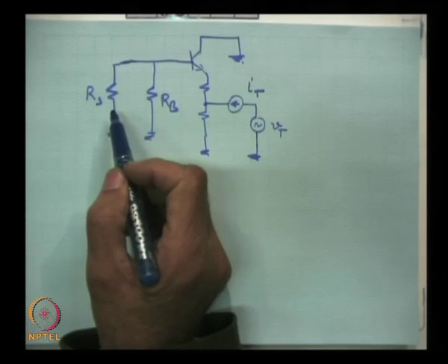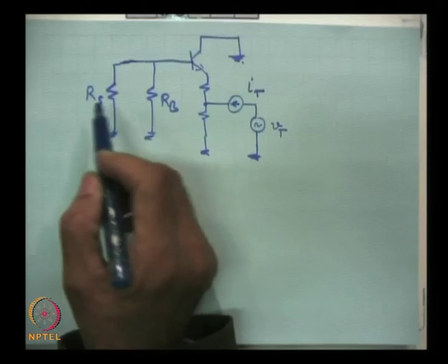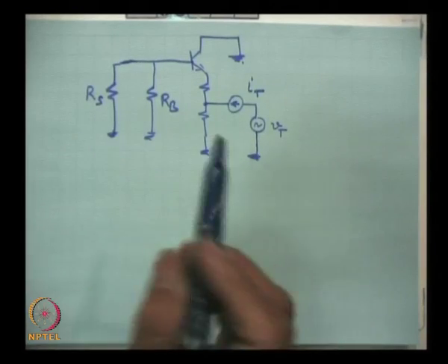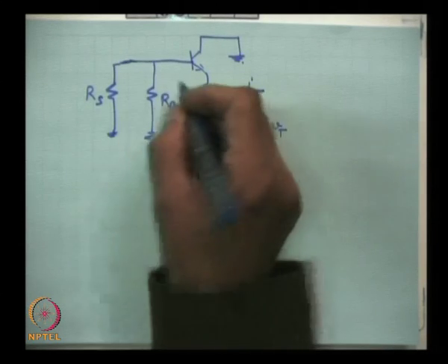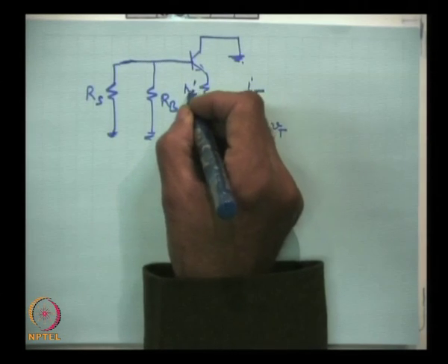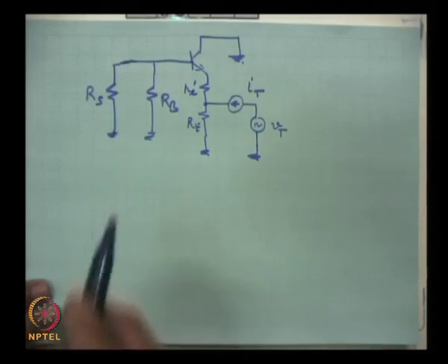This is like, suppose you are talking into a mic connected to the amplifier. Whether you are speaking or not speaking, that means whether the microphone is in actual use or not, the resistance of the coil will be in the circuit. So, when the signal is reduced to 0, still its source resistance has to be considered. So, this is the circuit, and this resistance is Re and this is Re prime.